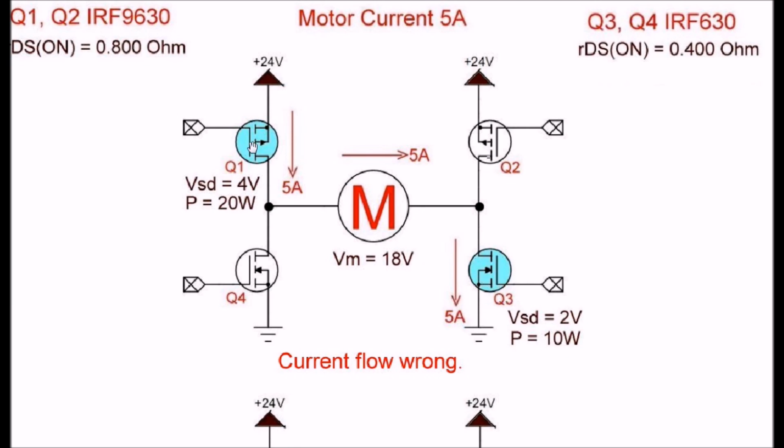Are these arrows pointing at the current flow? Really? Remember, source to drain current flow, but the arrow is pointing 90 degrees the wrong way. So, no, the arrow does not stand for pointing to the current flow. It points to the N-type material.